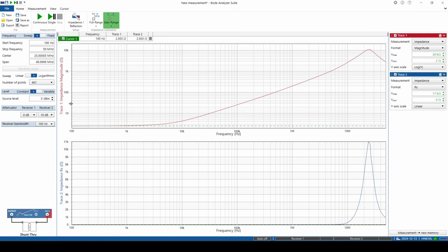But now we have our inductance value and we have our DC resistance value, so 2.5 ohms and about 47 microhenries of inductance. What we're interested in now is figuring out our capacitance, our parallel winding capacitance, and our parallel resistance due to magnetic loss.